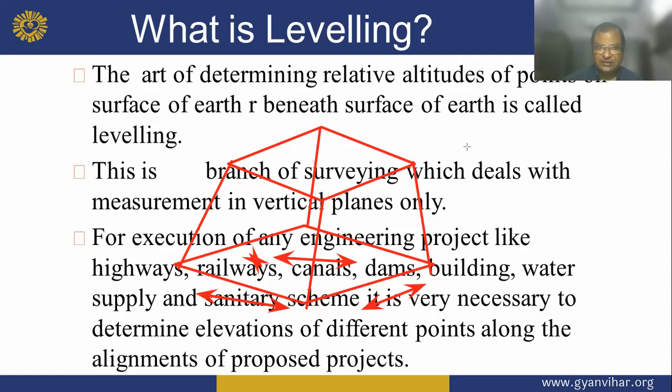But your land is like this. So can you construct on that land? No. First, you will make it level and you will remove the undulation. And after that, my dear boy, you will construct the building.